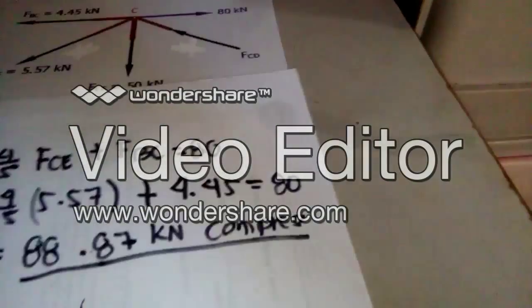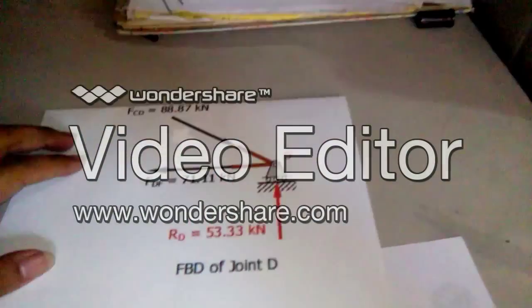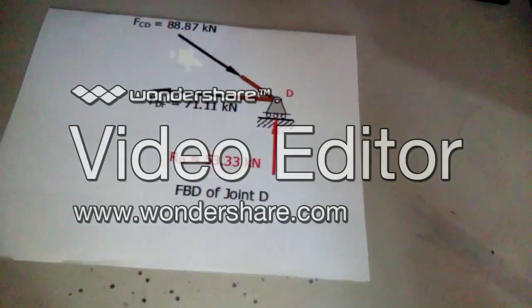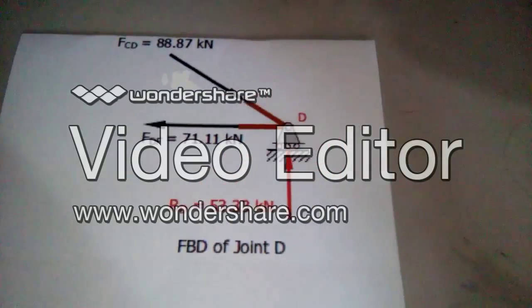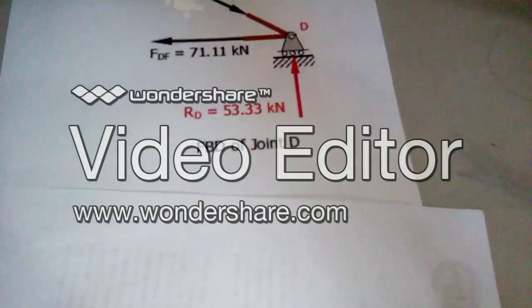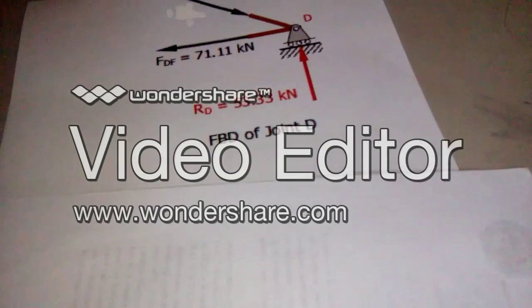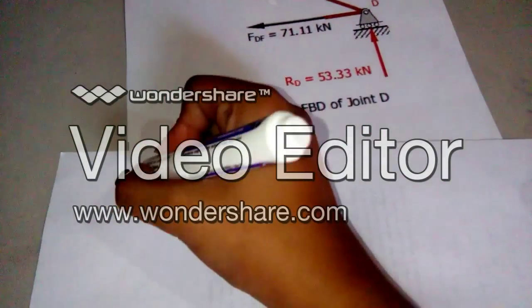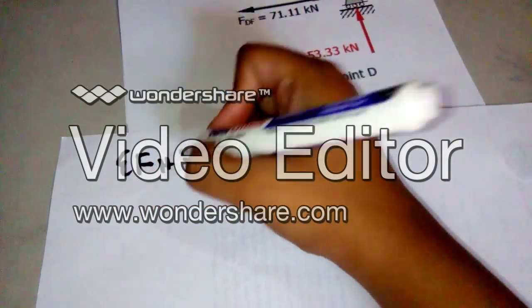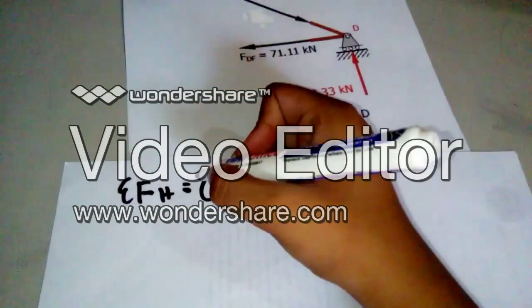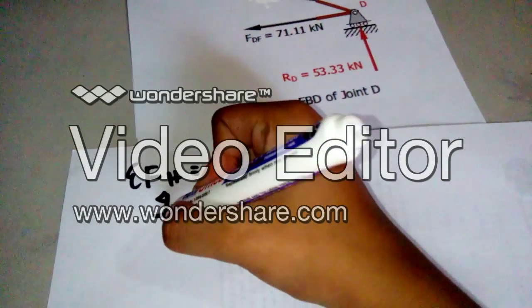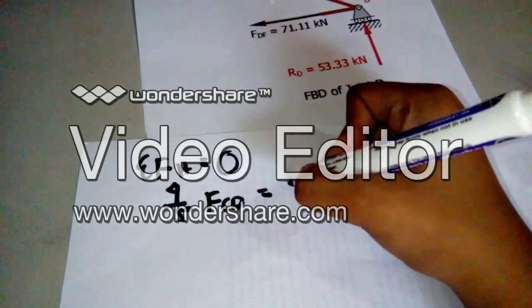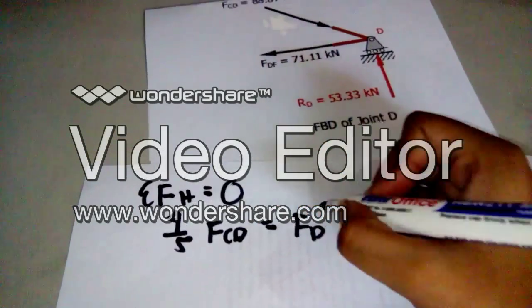And lastly, we have the FBD for joint D. The summation of horizontal forces in joint D is equal to 0. We have 4/5 FCD is equal to FDF.